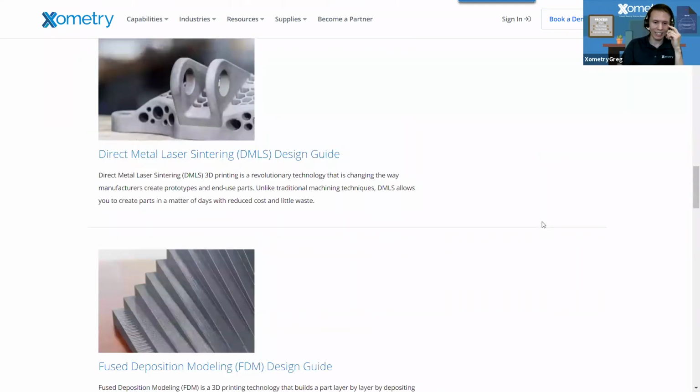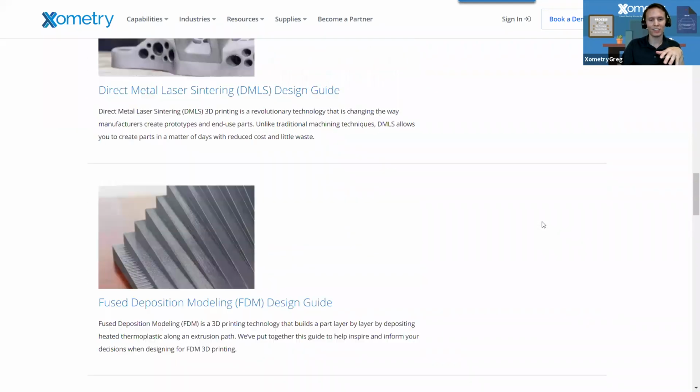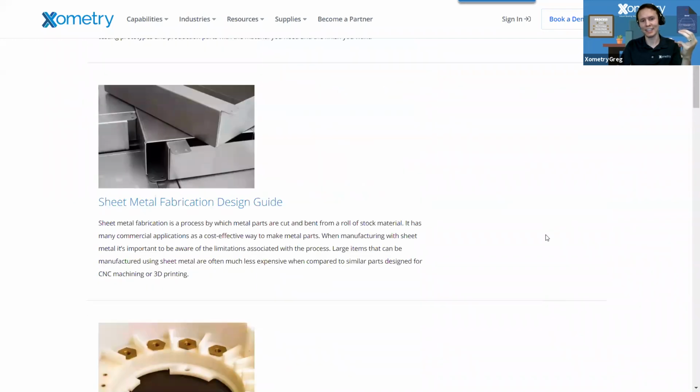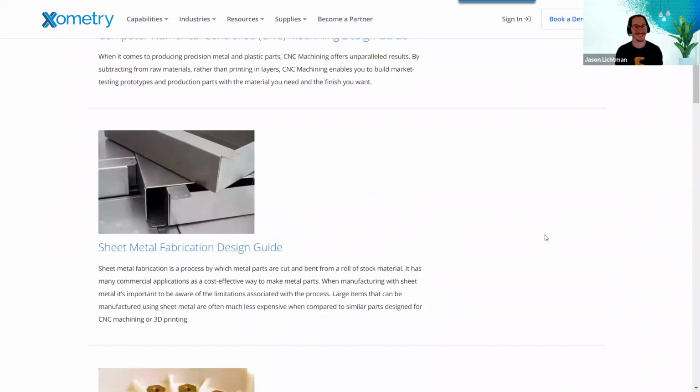Yeah, absolutely. And I actually talk about sheet metal in particular. One does not accidentally design a sheet metal part. It's one of the most intentional fabrication processes out there. But you may not know too much about bend radii or tolerancing, because tolerancing is really interesting in sheet metal because there are different classifications. There's a feature to feature on the flat pattern tolerance.